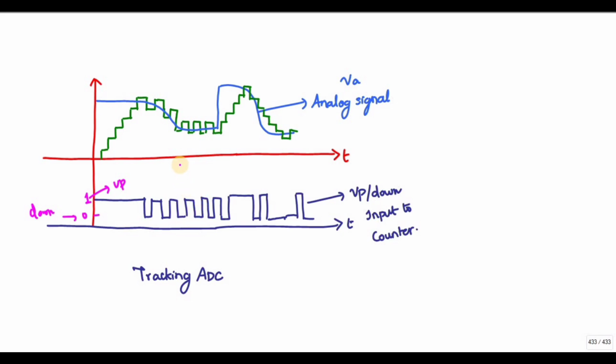You can see this process goes on repeating, with the digital output changing back and forth by plus or minus 1 LSB around the correct value. The tracking will be correct whenever the change in the analog input is very slow, within the 1 LSB value.